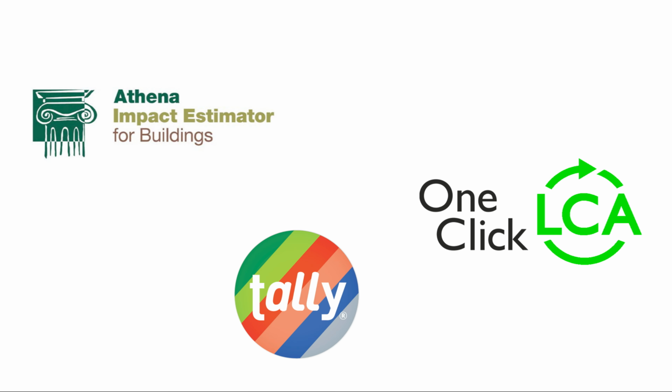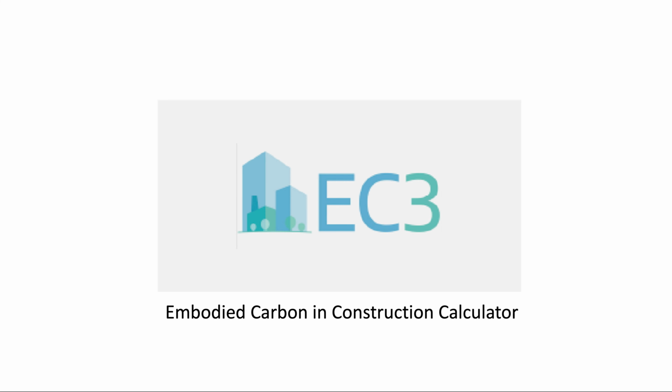In embodied carbon discussions, it is also important to be aware of embodied carbon assessment tools. Lifecycle analysis tools such as the Athena Impact Estimator for Buildings, Tally, or One Click LCA are all great tools to estimate embodied carbon for a project. The Embodied Carbon in Construction Calculator, EC3, is another great tool once projects reach the material specification and procurement phase. This tool is based on a database of product-specific, third-party verified environmental product declarations (EPDs) that could be used for embodied carbon assessment.